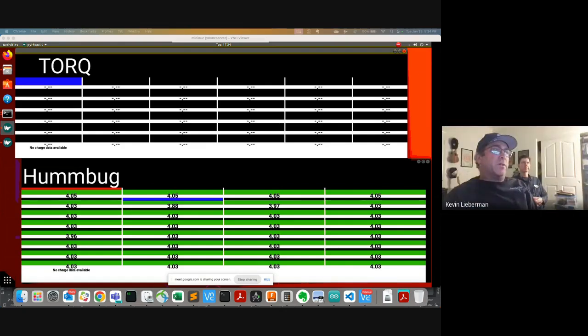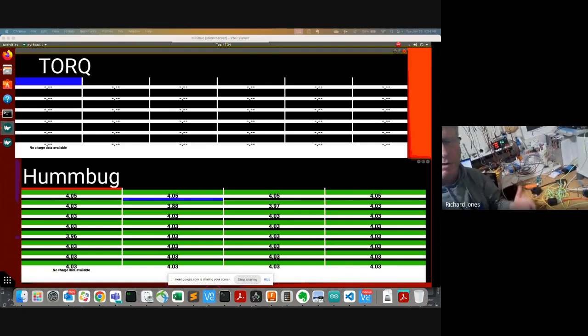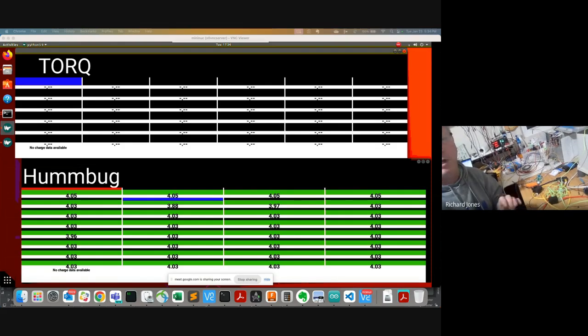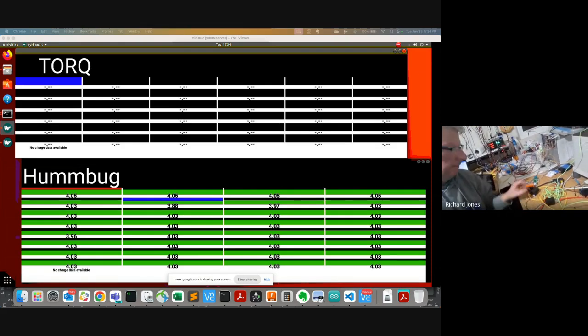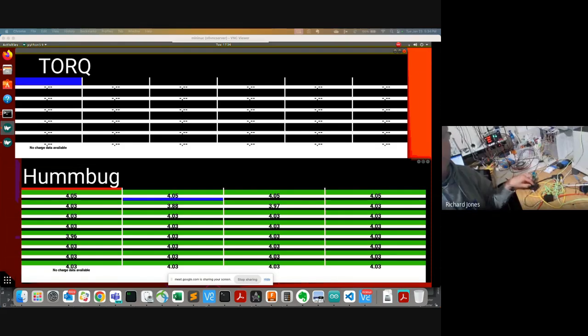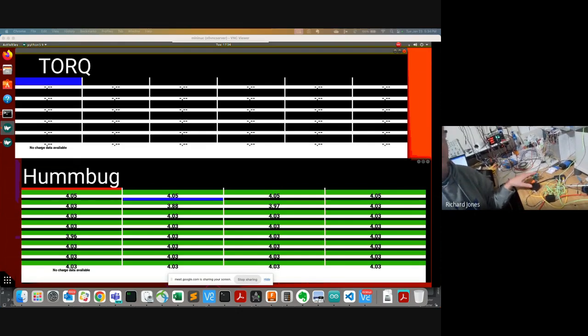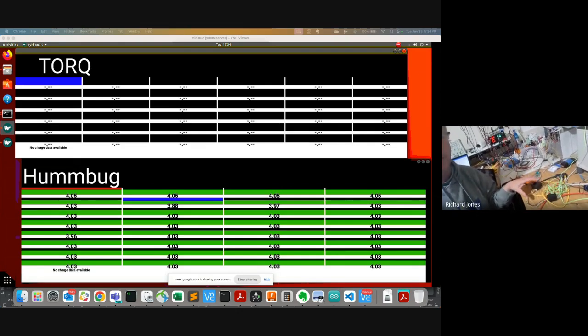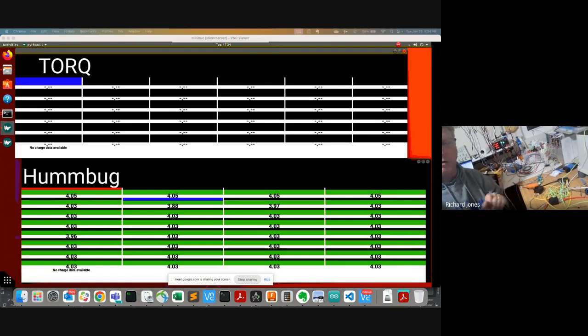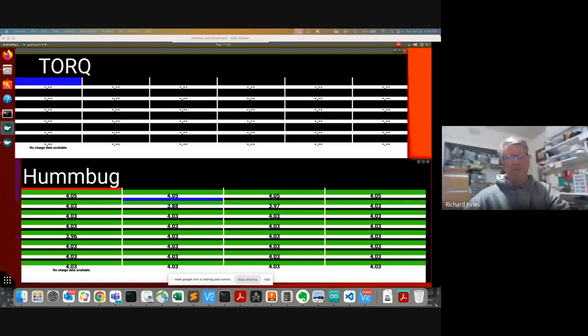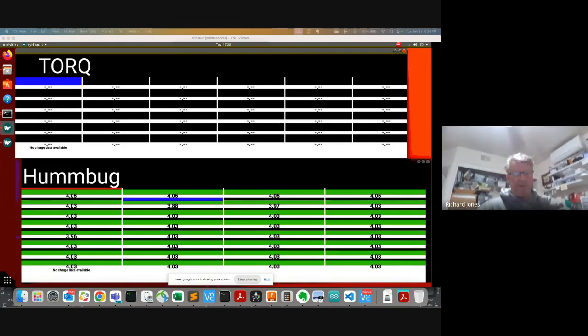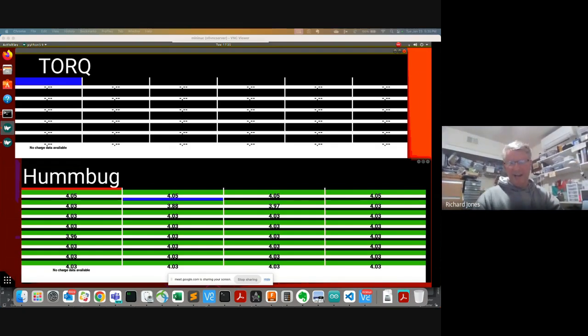But there may be a much simpler way to do what you're trying to do. We can build a current sensor using an analog circuit, where you could build it a lot cheaper. Because these have CAN bus on them, which is what we're talking about today, they tend to be a bit more expensive, but you can read current pretty accurately with just an analog to digital converter. Anyway, sorry, that was my little aside there.